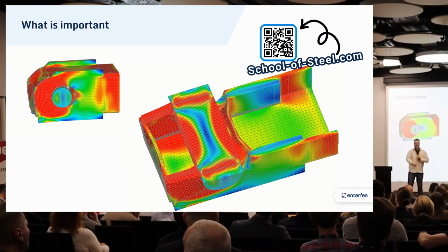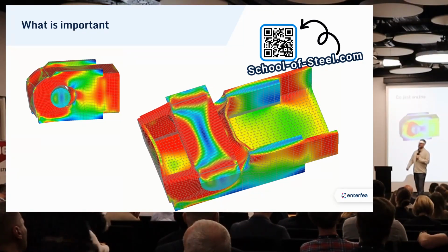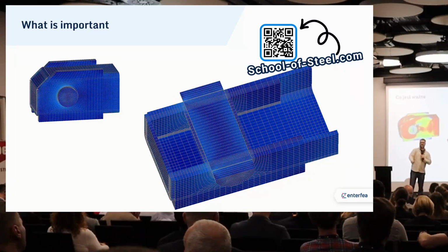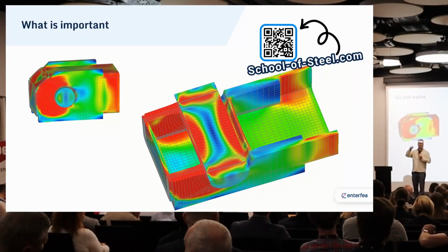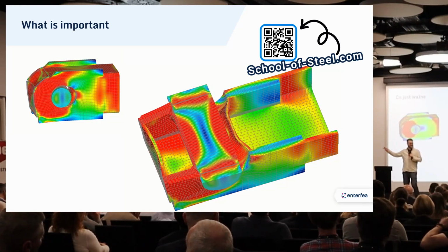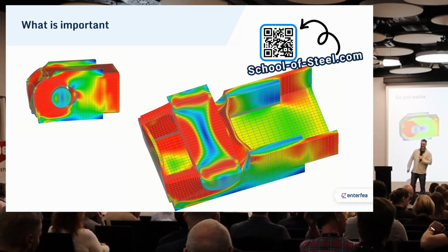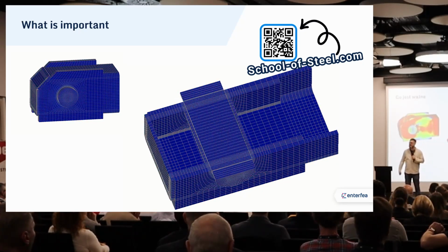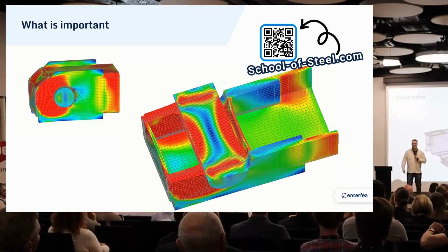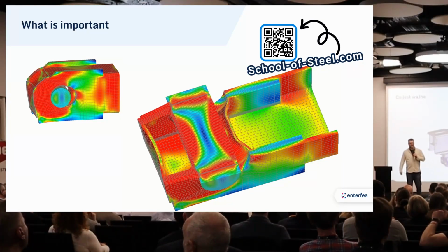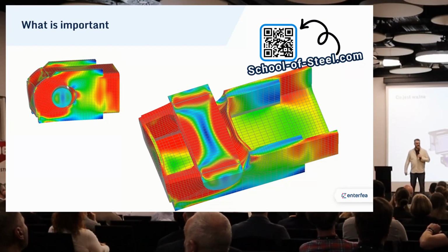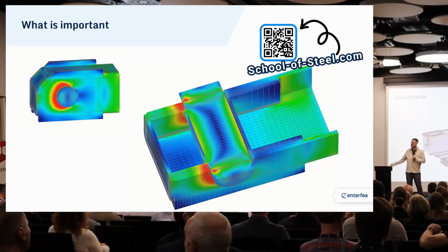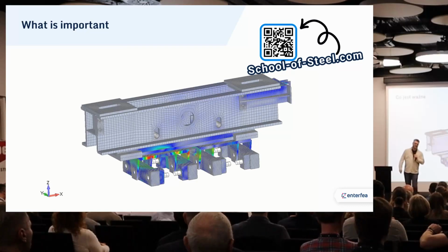Imagine that you have an element like this, and it fits between two plates, so you cannot add external plates, and realistically, the only way you can strengthen it is to drill a bigger hole and weld the tube inside. And you hope that this tube somehow will take at least a little bit of bearing stress and transfer it to the other end of the opening. And this is how you wish to strengthen the connection. There are no code rules for that, and in such a case, FEA is your only friend.